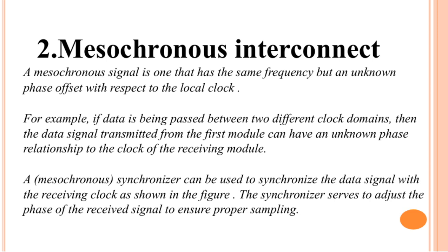This synchronizer adjusts the phase of the incoming data signal to align it with the receiving clock. By doing so, it ensures the data is sampled correctly, preventing timing errors and data corruption. Essentially, the synchronizer bridges the phase gap, enabling reliable communication between the two domains.